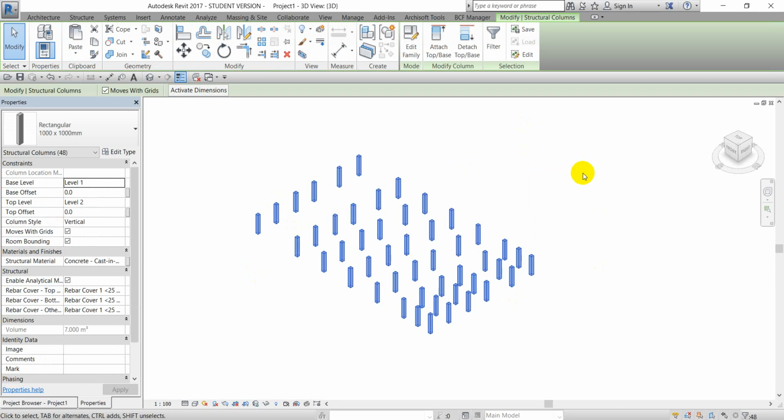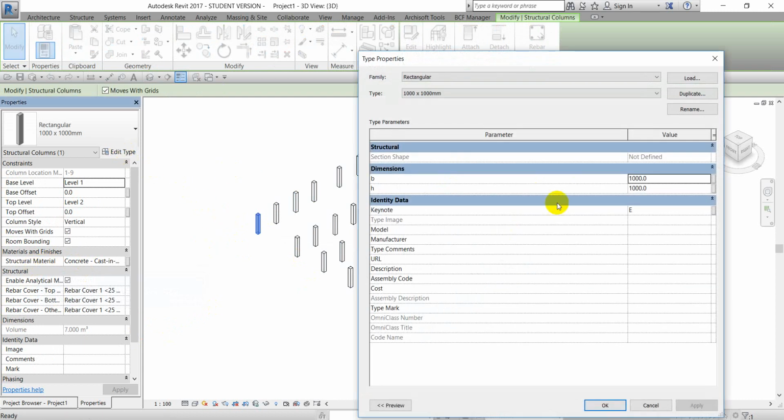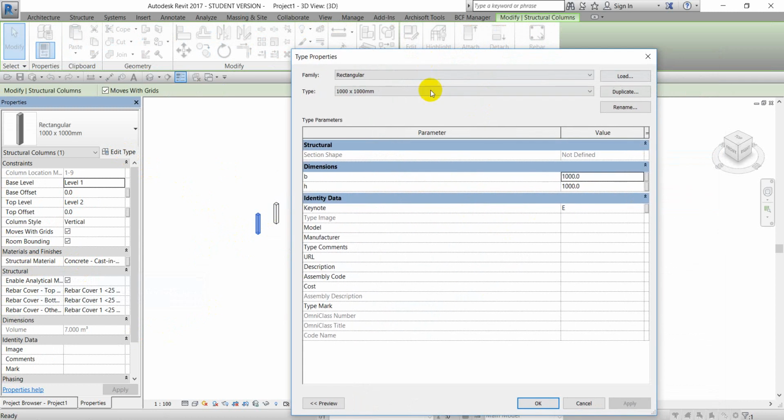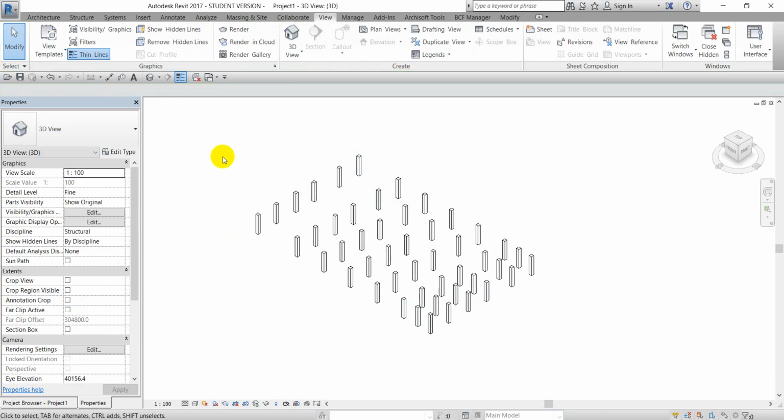Just let us see how to change that. You want the column type. If you want to change the column material, you have it in here. But if you change in here, only one column will change material. If you want to change all the material, you have to go into Edit Type. You have to change from this one. But for the one, I think after I click the back category. No, not beside, yeah, this one. No, you have to click this one. You click this browser.